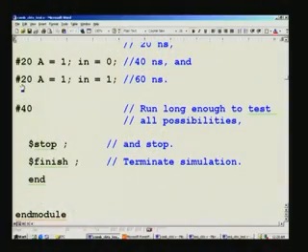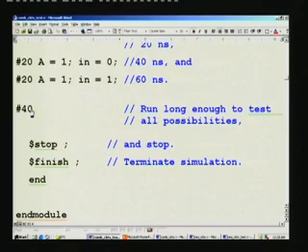And then we have almost finished the test bench. So, easy it is. Now, we have already accounted for all the combinations, we give a little more extra time, we run for a little longer time, so as not to miss any information. For example, it will take another 20 nanoseconds to complete that 1 1. So, it would be sufficient if you put just 20 here, and you can put any number, there is no hard and fast rule for that.